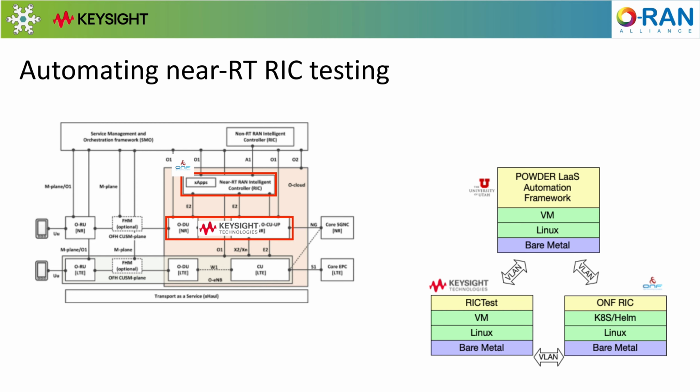The figure on the left shows the realization of this scenario in the ORAN architecture. So the system under test is the ONF SD-RAN near real-time RIC and the KPI on xApp. And Keysight's RICtest is emulating RAN nodes with E2 interfaces and also emulates the O1 interfaces of those. It provides traffic models and emulated UEs as well.